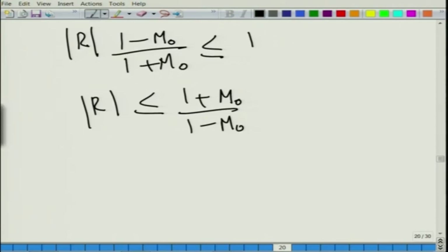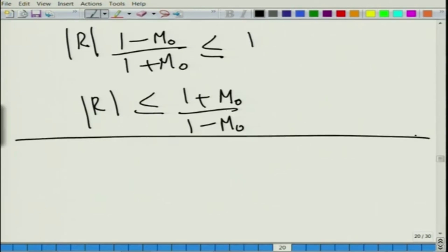So, that is one thing that obviously comes out of all these calculations, and clearly the total aeroacoustic power that is given through a tailpipe. By virtue of all the expressions that we derived so far, the reflection coefficient for the classical wave variables can be greater than 1 when you have a non-zero mean flow in a duct, but in typical cases it is less than or equal to 1.